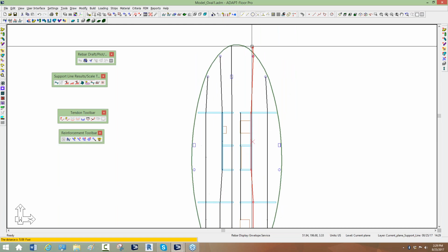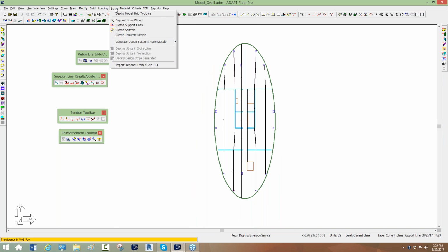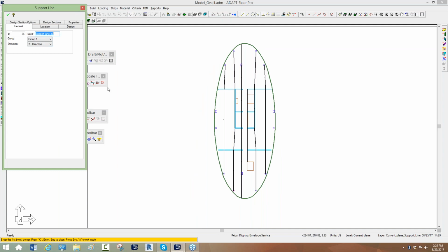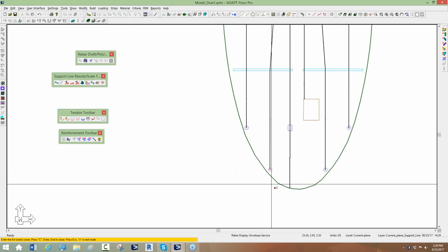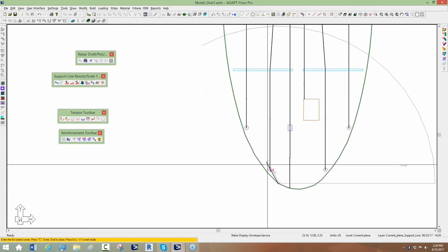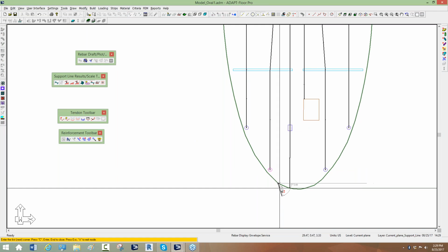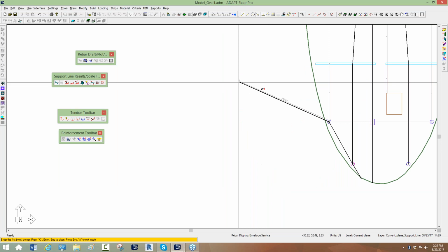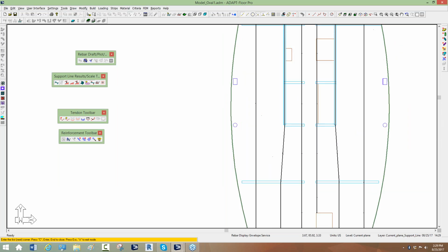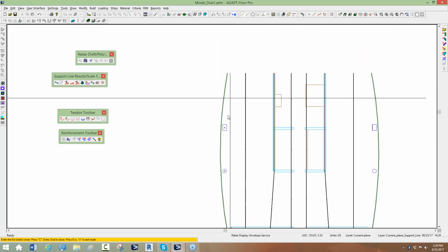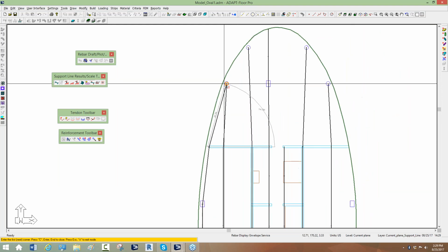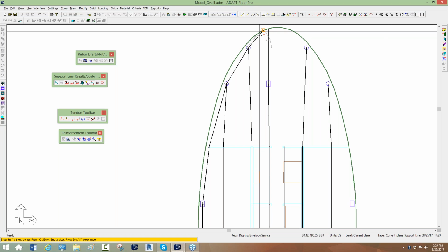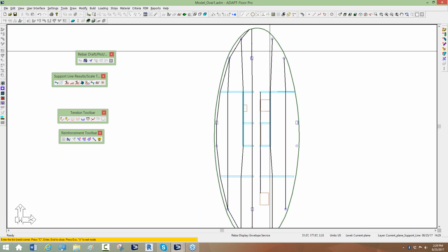So let's do that. I'll go ahead and introduce a new support line. This will be in the Y direction, and I'll start that support line here. This is just some cantilever off the edge of the end of this column, and then this support line will just wrap around the perimeter of the slab on this side, and I'll do the same on the opposite side. And maybe we'll stop that there.